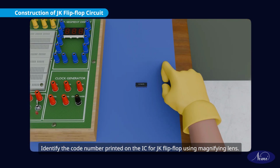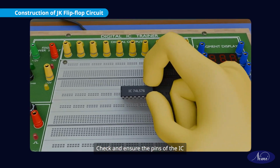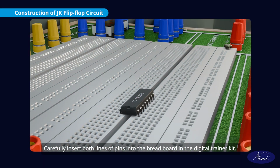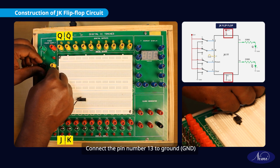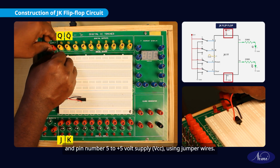Identify the code number printed on the IC for the JK flip-flop using a magnifying lens. Check the pins of the IC and align it in the right position over the breadboard. Carefully insert both lines of pins into the breadboard in the digital trainer kit. Connect pin number 13 to ground GND and pin number 5 to plus 5 volt supply VCC using jumper wires.